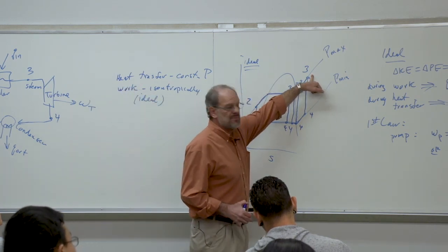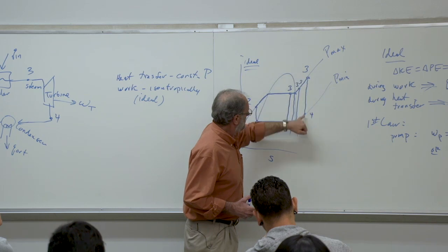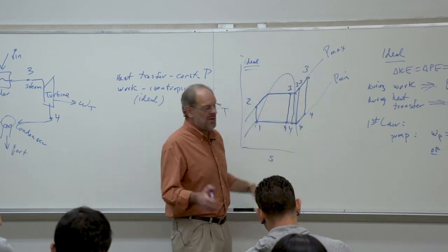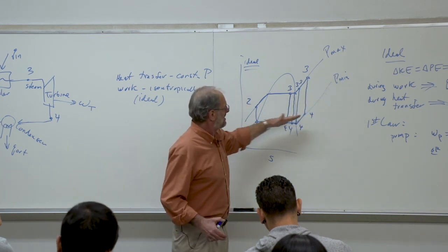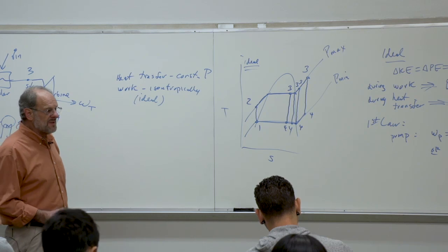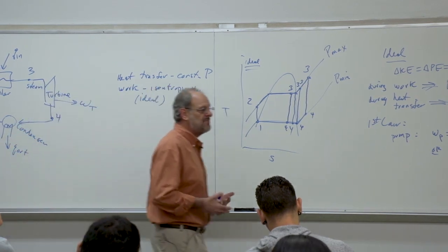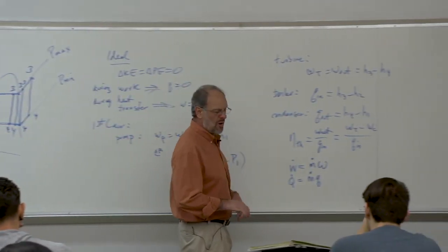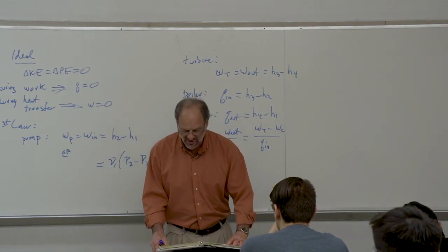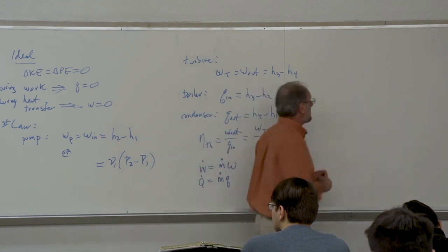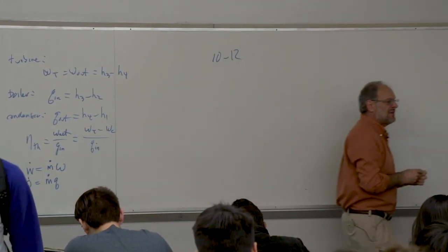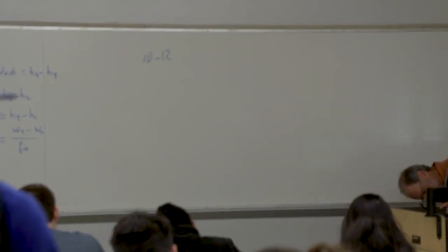We know state point 3, that's typically given. It's isentropic from 3 to 4, so we look up S3, that equals S4, and at S4 and at the minimum pressure, which would be P4, well, we just look up the enthalpy at point 4. So we're going to use our steam tables, we could also just call them water tables, rather than any kind of ideal gas table, so please make sure you're very careful on this. So let's begin. Let's look at problem 10-12 in your version of the textbook.